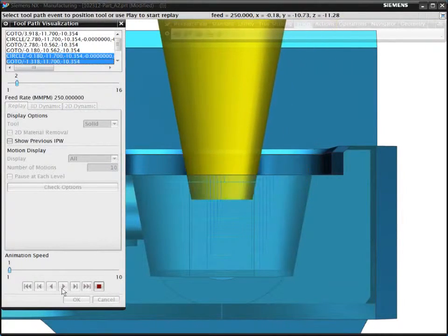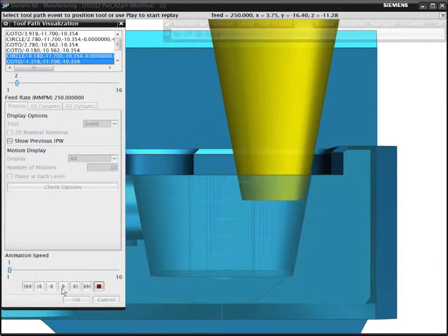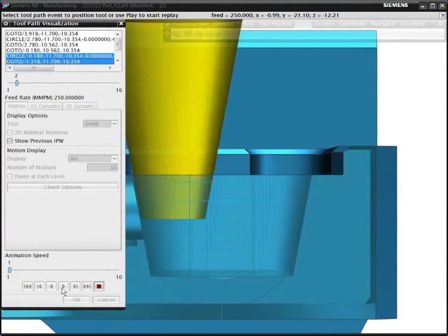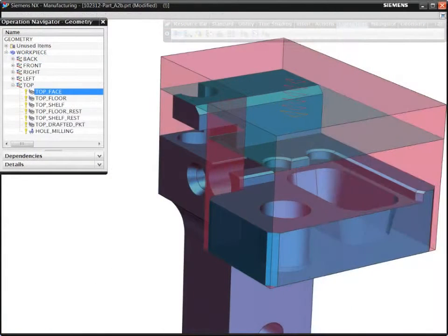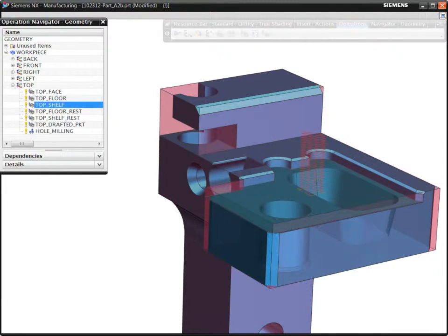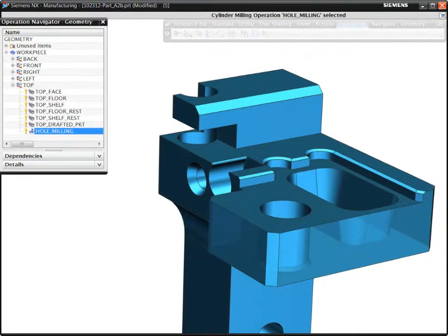In summary, the volume-based milling provides automation that helps you to program prismatic parts quickly and easily. NX automatically calculates the machining volume from selected floors and walls, thus eliminating the need for multiple containment boundaries. To validate your programming decisions, NX displays the current in-process workpiece and the cutting regions. NX automatically creates smart toolpaths that are safe and efficient by tracking the uncut material. Customers report 8 to 10 times faster programming with volume-based milling.